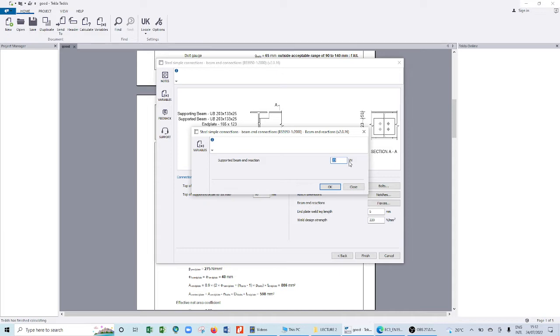New model, depending on the purpose of the unit. Then given the load generated from loading. So I'm just going to imagine that, okay, from the model we have, was it 5.717 kilonewton per square meter? The average weight. And this was including the load of the roof. So if the load, you can check it in Tekla, you can just keep it there.